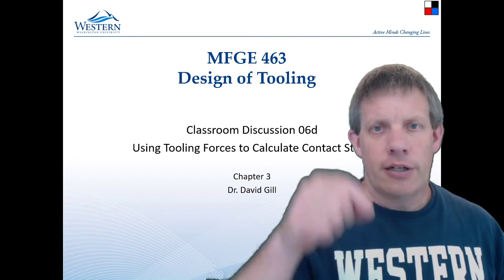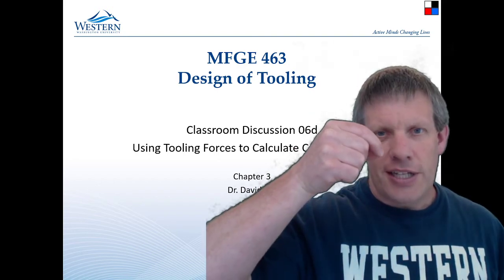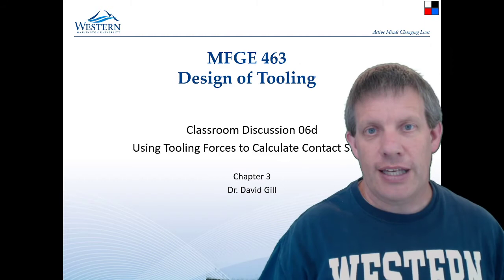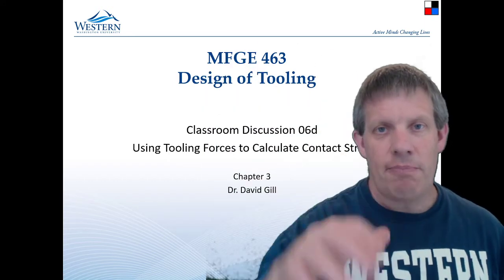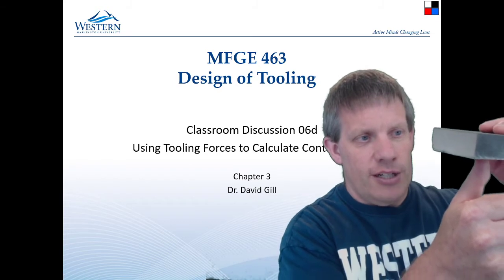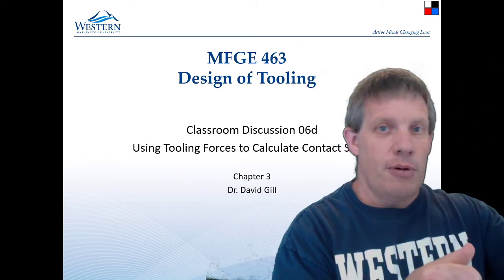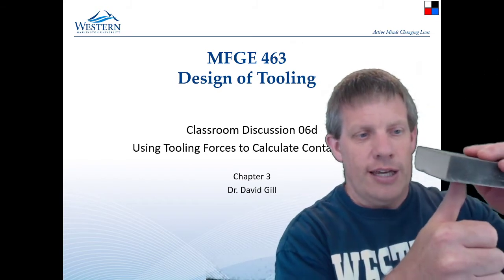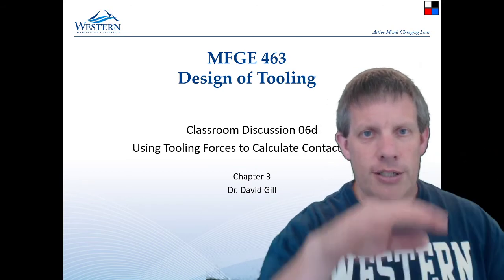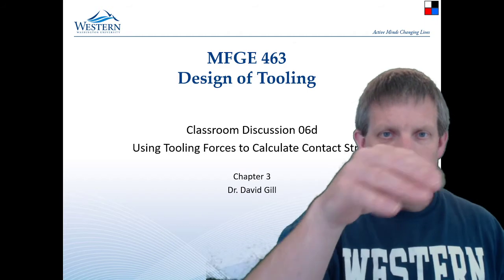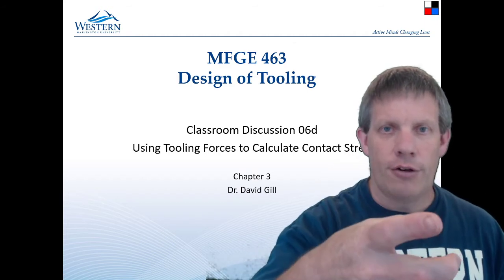But the calculation is really hard, because as I press down, when it first touches the end of a sphere, the contact is just a single point, so the pressure is enormous. But we're going to deflect either the part or the spherical locator, and pretty soon our contact is going to be a little bit of that hemispherical section. It'll be round in cross section.